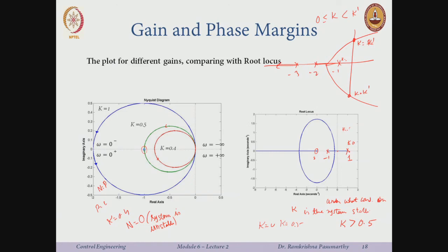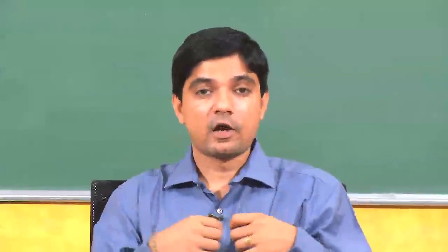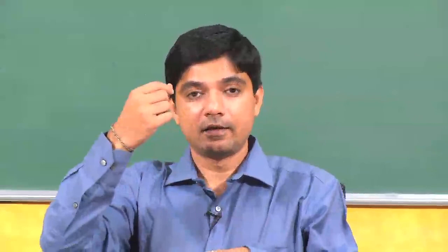So, I start with an open loop unstable system, and the system is unstable until I have a certain gain. Therefore, we call these systems a system with a negative gain margin. The earlier problems were formulated in such a way that how much can I increase the gain k before it becomes unstable.